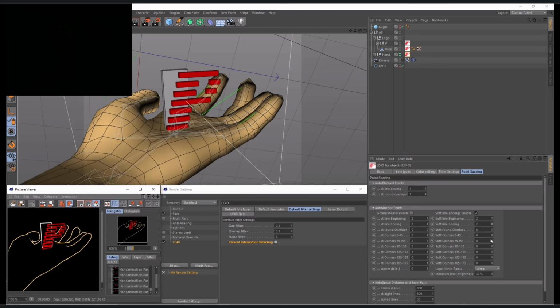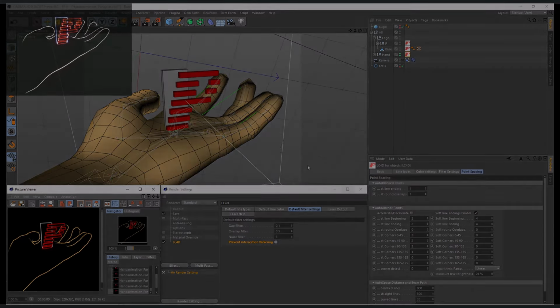So you need to play around a little bit until you get the best result for you. And in my case, the minimum brightness level and this setting with the density will show the best result and looks already better, I think. Important to mention is that this feature will also slightly reduce the point density, since faded-out points are not scanned anymore.